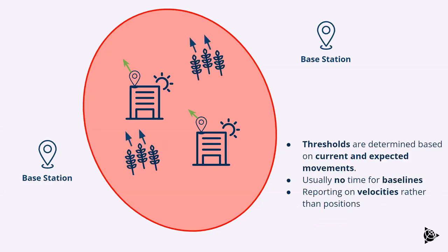The second region of influence is one that's already moving. This is really typical in landslide or regional settlement or seismic monitoring, where the things are already moving. And so we want to set these up reactively and understand if things are stable. So if we're looking at a fault line that's moving or a landslide that's moving, they tend to move very slowly over some period of time and then accelerate and move a lot at once. So we want to understand, again, that natural, stable movement.